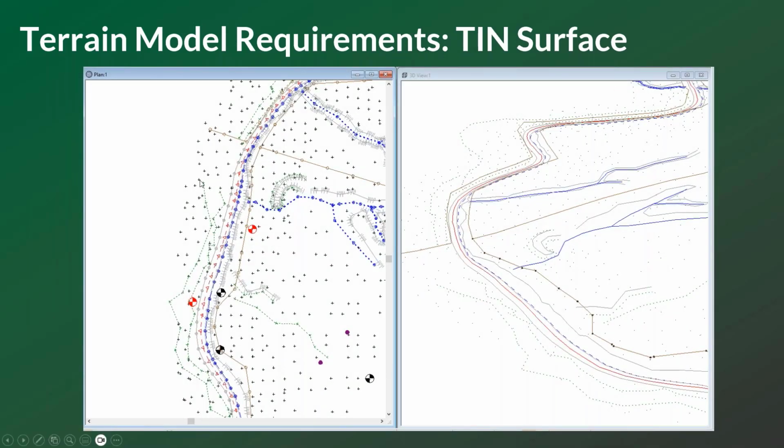These are our survey points. And right now, this is just with the data imported. We don't have a surface, and you can actually see that here, because in a 3D model, you would typically, if you're using default settings, see that 3D surface. So this by itself is not enough to base our road design on, because we don't have a complete surface.